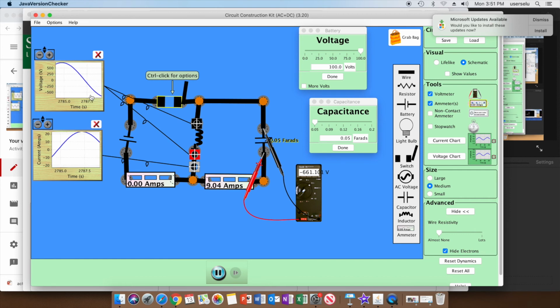You can see how an LC circuit can give you an incredible voltage advantage by the energy you store in the electric and magnetic fields. So there's essentially a 700 volt potential being output by this inductor. And notice that it's completely sinusoidally oscillating. It's perfectly periodic in nature. Now it's a fairly slow oscillation, which means that it's a fairly low frequency circuit.